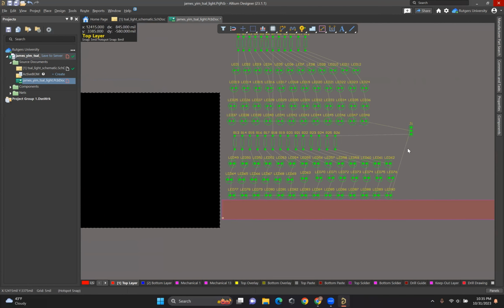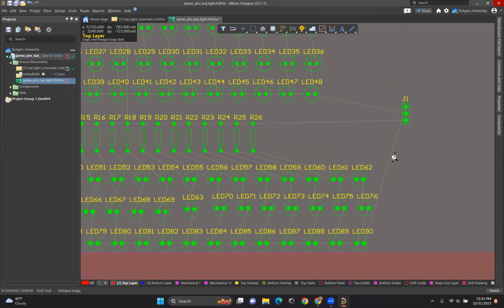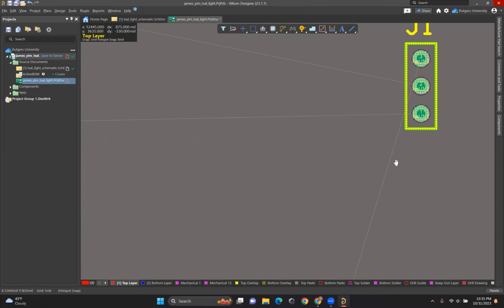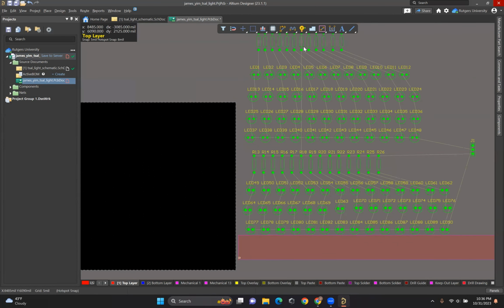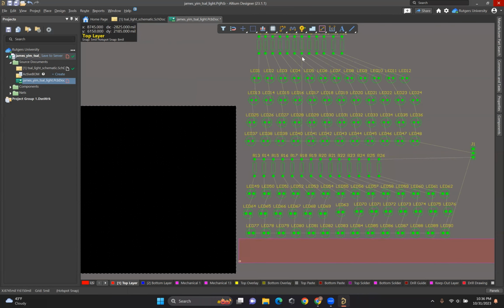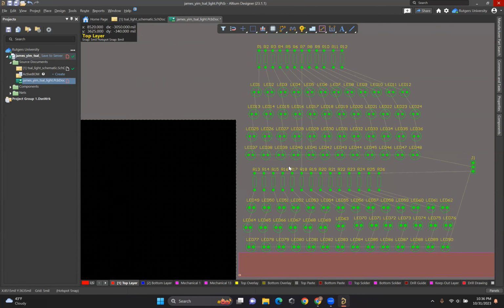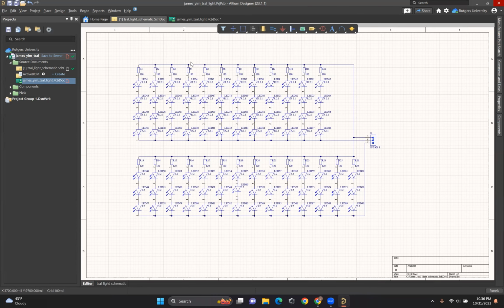Here, you can see these lines. These are nets, and you can even see them on the labels. They're labeled. So that's just the nodes that they're connected at electrically. It pretty much just draws the nets to the closest point which is on the same net. That's why this wire is connecting down to these. That's the same thing as this long connection that's connecting down here.